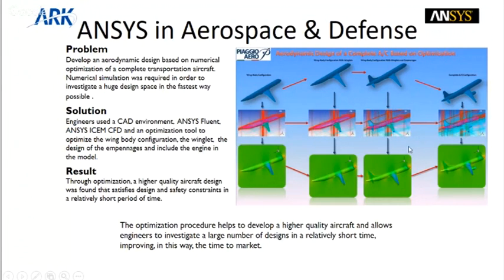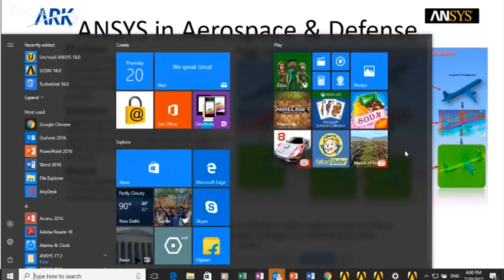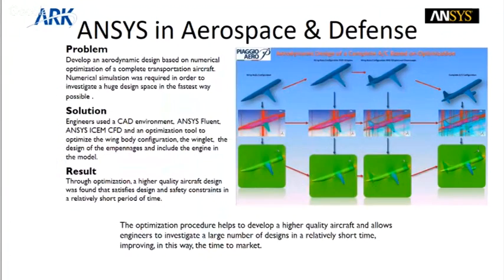So we have done optimization for this. This is an aerodynamic optimization for the same case study. We have done optimization for the structures as well. As I said earlier, it may be your material, it may be the size and shape of your inner parts in the aircraft which strengthen your aircraft. By doing the optimization study, a higher quality aircraft design was found